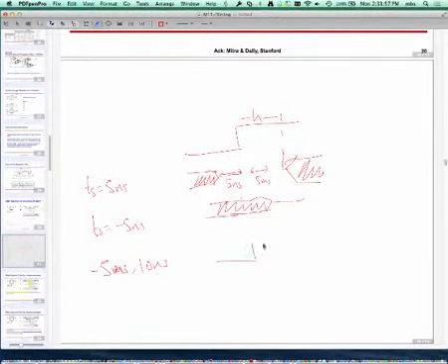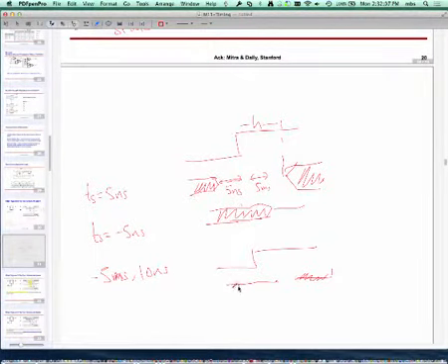Then that means in that flip-flop, this is the band of time of stability, where this is 5 and this is 10, right? So it's going from TS, the clock edge minus 5 nanoseconds, which means clock edge plus 5 nanoseconds, through clock edge plus 10 nanoseconds. Okay, so it should remain stable in this duration.